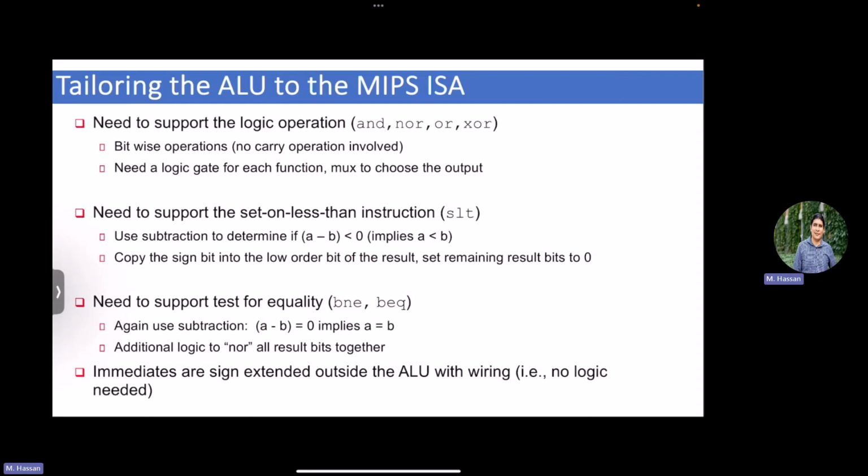Shift operations, if you think about them, are just really putting the wires in different places. You take the register value and, instead of starting from bit 0, you start from bit 1. Then you either rotate or do sign extension, the things related to signed and unsigned that we discussed earlier. The shift operations are usually very, very easy to do. What is the format of this? Well, we already mentioned that the shift and all the logic operations are part of the R format of the arithmetic. So again, you have the opcode and the function.